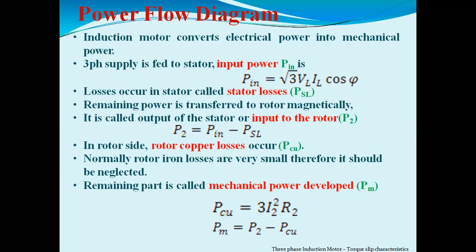And the remaining power we are saying is the mechanical power. So we can take that power as 3I2²R2. Here we are taking 3 because it is a three-phase induction motor. So here we have the equation. What equation do we have? We have P2 equal to Pin minus PSL.